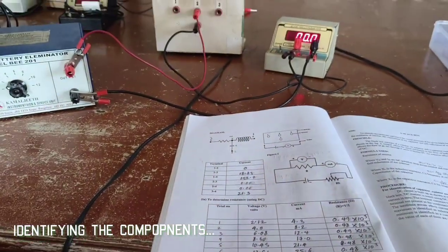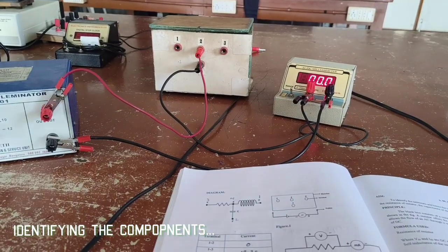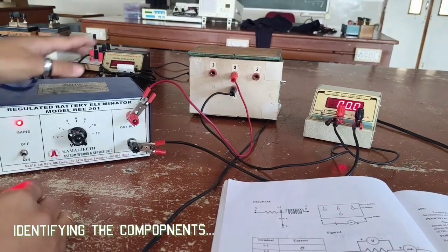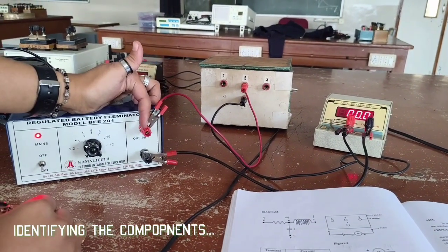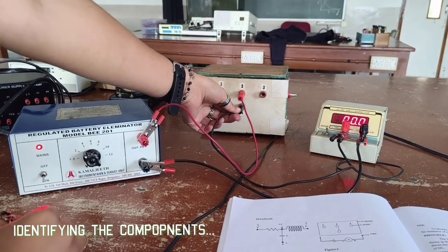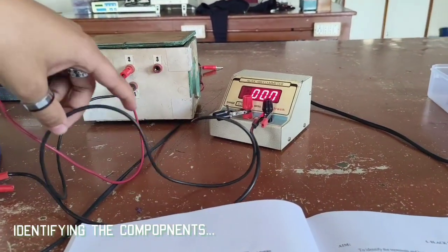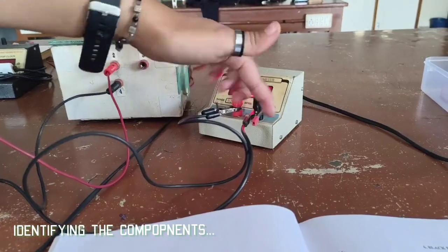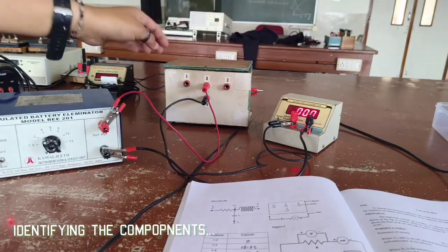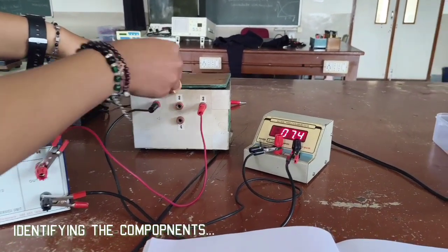We connect a battery eliminator to the black box and an ammeter, and based on the values of current, you can figure out which branch is which. When connecting, you start with the positive of the battery and connect it to any one of the terminals of the black box. Then you connect another terminal of the black box to the positive of the ammeter. Then the negative of the ammeter comes back to the negative of the battery. It's a really simple circuit, and these are variable, so you can change the position of each and see the values of current changing.